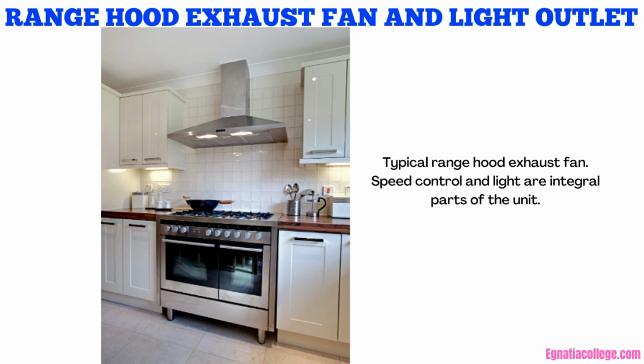Insulation must be kept dry to maintain its effectiveness. For example, a 1% increase of moisture in insulating material can reduce its efficiency by 5%. Humidity control using a humidistat connected to an exhaust fan is covered in Unit 16. Building inspectors require the vapor barrier to be intact around all outlet boxes on the outside walls of the house. It is the electrician's responsibility to maintain the integrity of the vapor barrier, Rule 12-3000 in Appendix B.